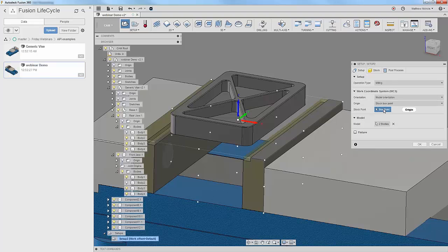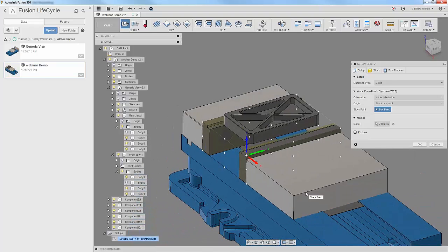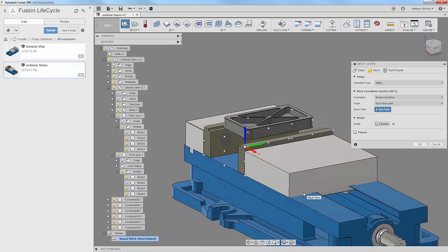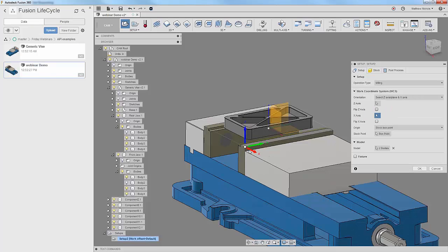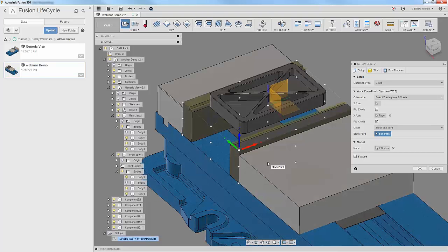So yeah, just in case somebody hasn't cut soft jaws, maybe a quick comment. When you're doing this, generally you would clamp the vise onto something like a 1-2-3 block or a 1/4 inch parallel. So you want a gap to get the tool in, but you want the vise jaw to be clamped. Quick tip for everybody. Yep. So like I said, not the way you would actually do it, but just doing it this way for now.